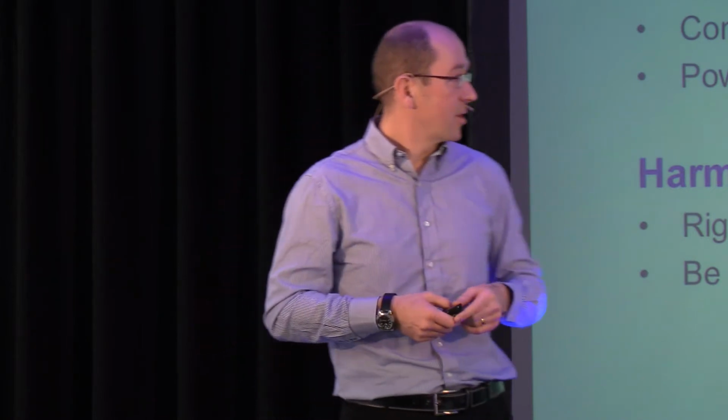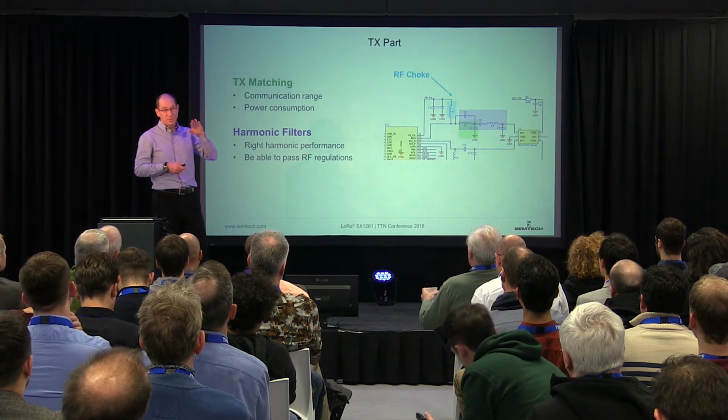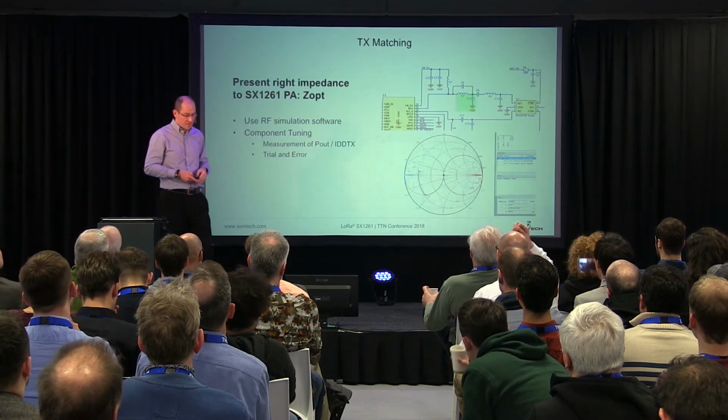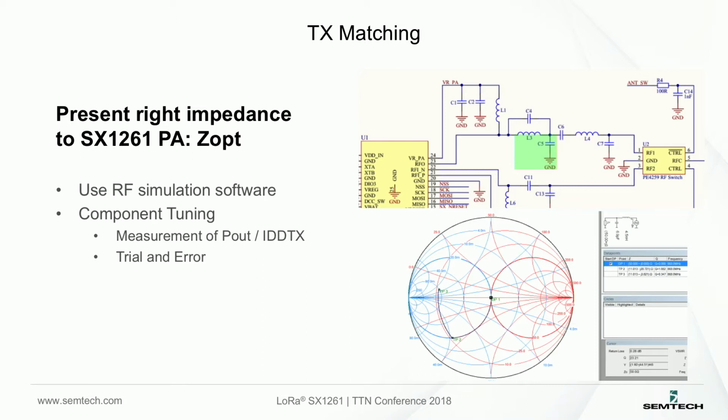And that's the aim of the second stage here, the purple stage. So harmonic filter, so that you reduce the RF noise to its minimum. A few words on this optimum impedance. It's actually the impedance that you present to the PA with those LC caps here. If you present a 50 ohm load at this point, you have this LC cap that transforms the 50 ohm to the opt point, so the maximum efficiency point, I would say.